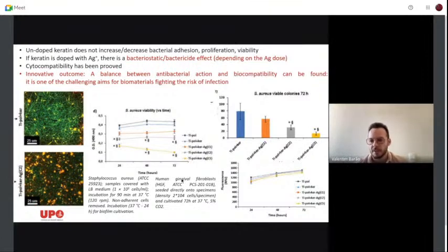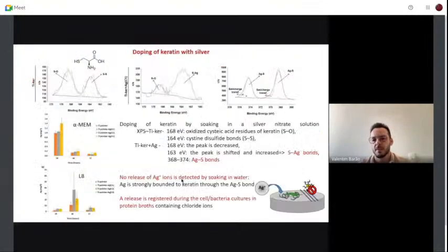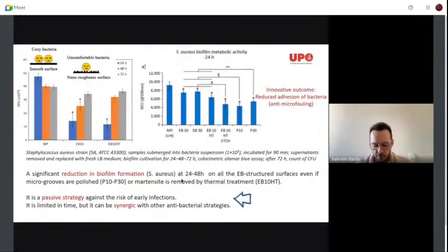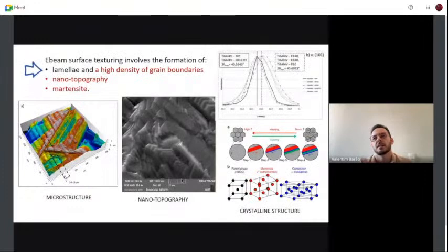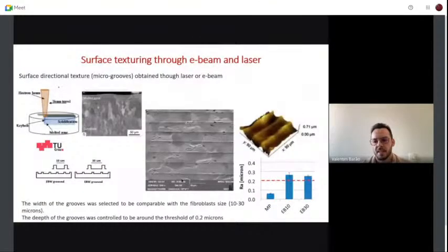The first one is about the laser texturing that you mentioned, that you were able to change the microstructure of the surface. My question is, if you change the temperature, the time of the treatment, and other parameters, are you able to create a titanium dioxide crystalline structure like anatase or rutile, thinking about photocatalytic action and so on, to have a more antimicrobial action?